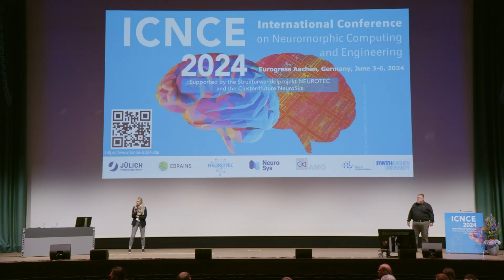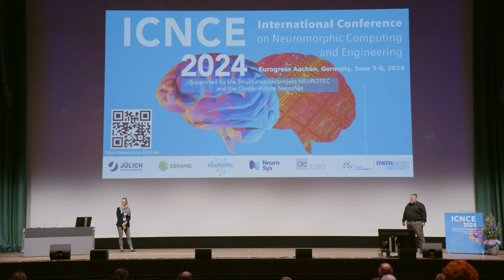Hi, my name is Deepak Sharma. I have one question related to signal integrity. The output of the digital to analog converter you are giving to the Memristor through multiplexers, right? And based on the state of the Memristors, you will be applying some writing pulses. So how are you taking care of the signal reflections? Because there might be the possibility of impedance mismatch when we do high frequency pulsing. Those reflections might create disturbance to the device. So how is it being taken care of in your case?